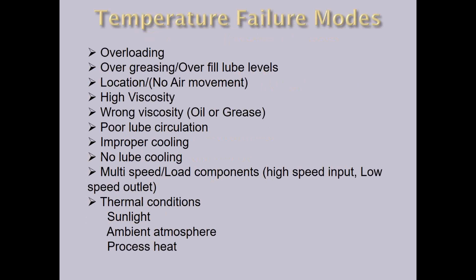So let's look at some common temperature failure modes. We have overloading. If we overload our equipment, we can create high temperature and cause the lubricant to fail a lot faster. Overgreasing. Putting too much grease can cause a high temperature. If we overfill, I do a little training session in my 8-hour course about when you overfill like a Gould's pump. If you put the oil level all the way to the top of the sight glass, that sometimes will cause that unit to run 10 or 12 degrees hotter. We have to get the unit down below the halfway point and even lower if we can, if we got good control, because it lowers the temperature and causes a condition that the lube will last longer.